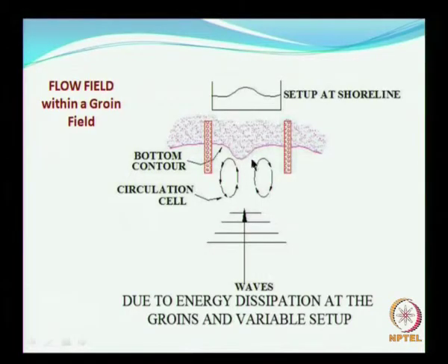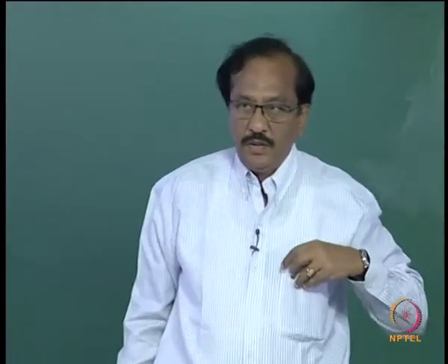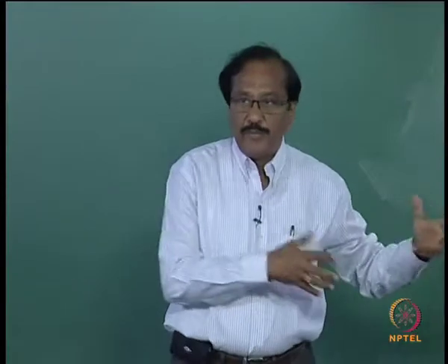So if the wave energy is less around this location, then the sand from locations of higher energy will get transported and start settling down, and that would result in the building up of the beach. So now you see the importance of the spacing between the groins.